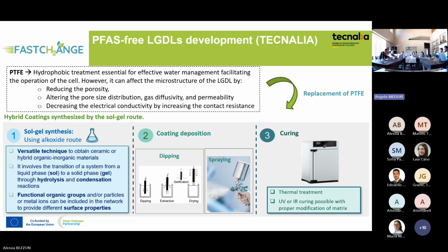Although it's less crucial than in fuel cells, in PEM electrolyzers the GDLs are usually covered with a hydrophobic treatment based on Teflon, which ensures effective water management, but it might reduce the porosity, altering the pore size distribution, or decrease the electrical conductivity by increasing the resistance. So what we are doing is substituting them, being careful that this is not happening.